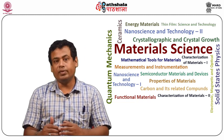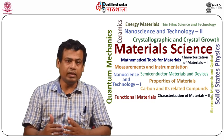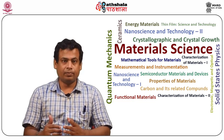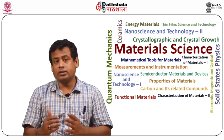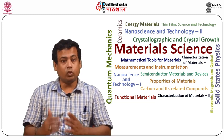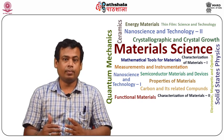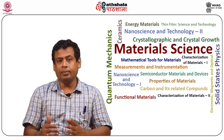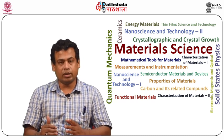In E-beam lithography, the key factor is the quality of the electron optics, that is, the ability to create a focused spot. The choice of resist, substrate and developer, and the process conditions of electron beam energy and dose, the development time and temperature are the key parameters that define the successful designing of nanometer scale patterns.